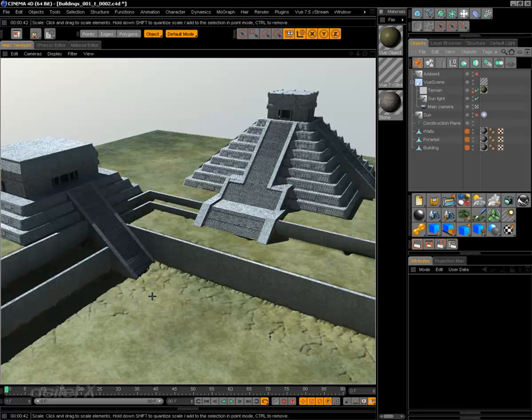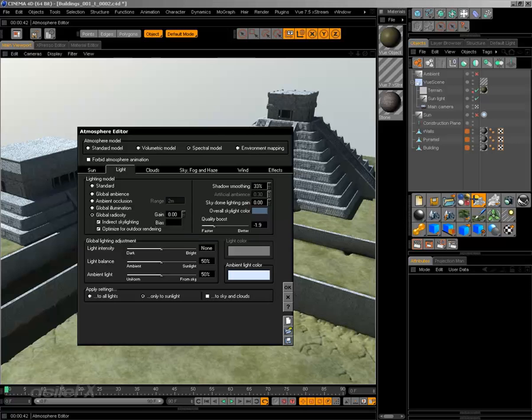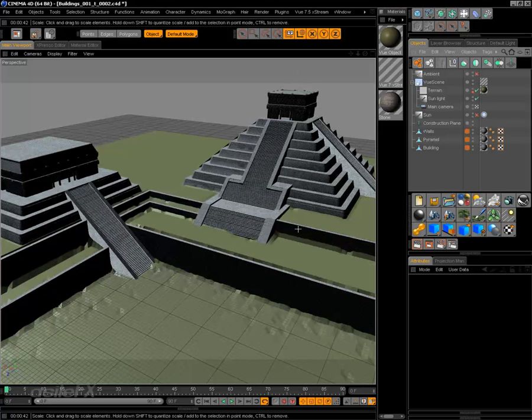And really the biggest problem you're going to run into is getting cinema objects to show their light on view objects. That sometimes works and sometimes doesn't. Typically when you're using the view radiosity setting and you have that turned on and the global illumination is turned off in cinema, then the objects transfer quite well back and forth.